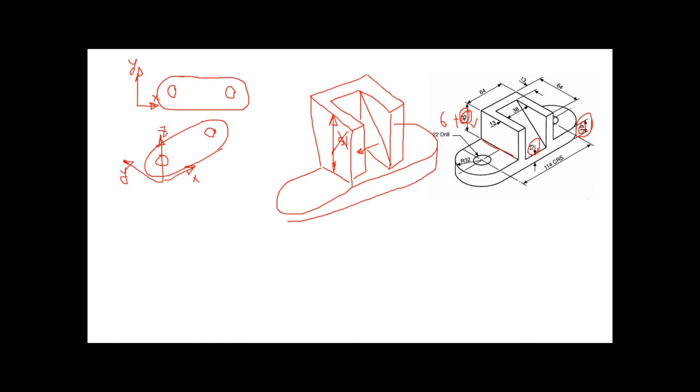Exactly, the extrude cannot work with the separate pieces because usually you draw this one as separate than this line. So the only one that can work for these cases is a press pull, not the extrude. Remember, guys. Once you make your extrude, you will end up having that surface, that part without the top, right? Clear, guys?